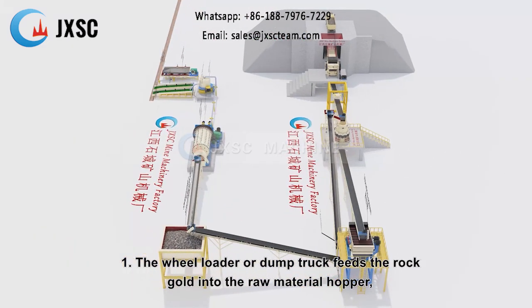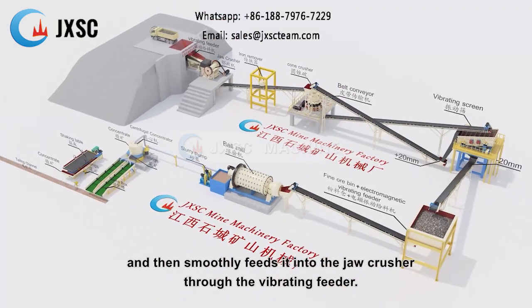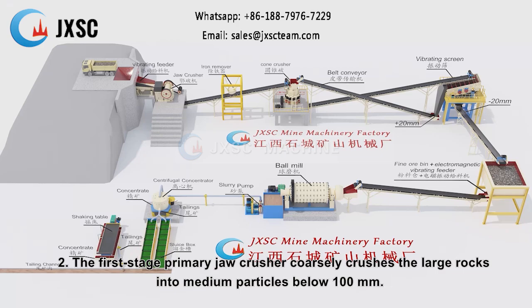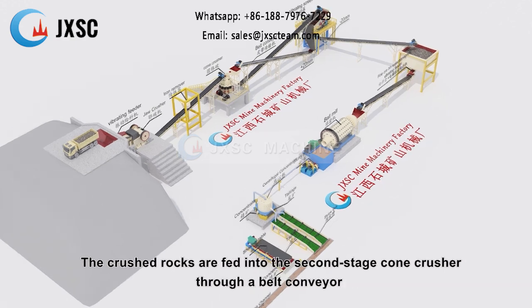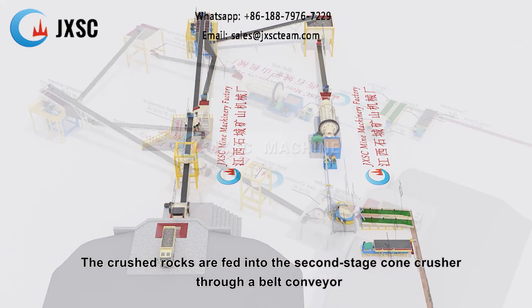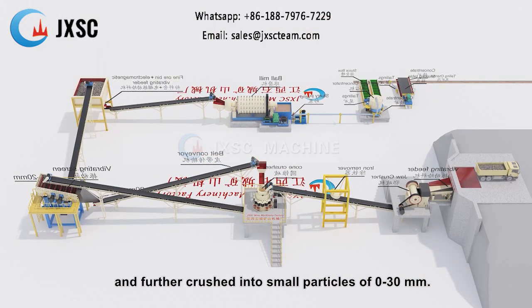1. The wheel loader or dump truck feeds the rock gold into the raw material hopper and then smoothly feeds it into the jaw crusher through the vibrating feeder. 2. The first stage primary jaw crusher coarsely crushes the large rocks into medium particles below 100 millimeters. The crushed rocks are fed into the second stage cone crusher through a belt conveyor and further crushed into small particles of 0 to 30 millimeters.